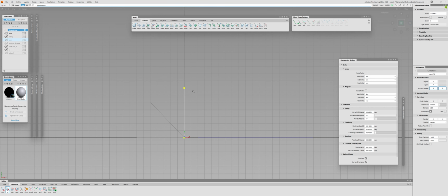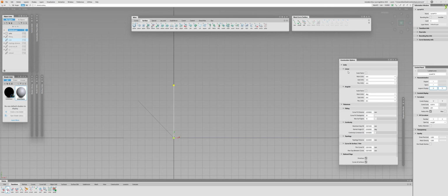And now, as the last example for the units, let's use the subunits and the pause units at the same time. I will rotate 45 degrees in minutes, and then 45 degrees in seconds. Click on rotate, hit tab, type 0, 0, 0 for my degrees, colon, and now 2700 for our minutes, and then another 45 degrees for seconds. It will be 145800, hit enter. And here we go. We rotated 45 in minutes and 45 in seconds. That's basically how it works. Now the linear works literally the same way.